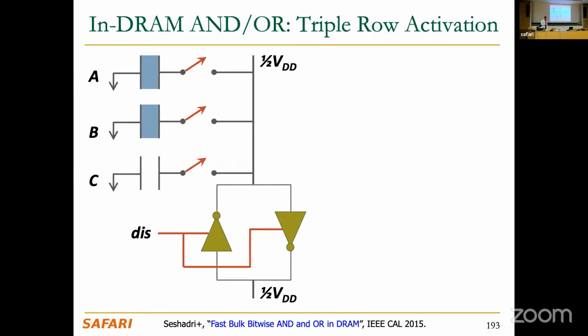So this is the key idea of Ambit. Before, in RowClone, I was accessing 2 rows simultaneously to do the copy. Now, instead of accessing 2, I'm going to access 3 rows at the same time. So you have rows A, B, C, and each one of them has a cell with some voltage level stored there. I'm going to send activate to all of the 3 rows at the same time. They are going to perturb the bit line. This perturbation of the bit line is going to be amplified into the majority of the voltage levels that were initially stored in the three cells. So the majority of the 2 here is actually a high voltage level. And this works like this because of the way this is a differential sense amplifier and the way that this is actually working.